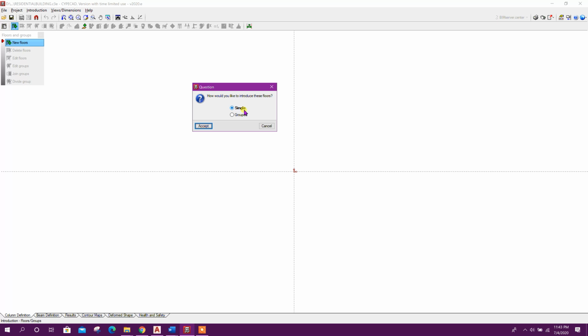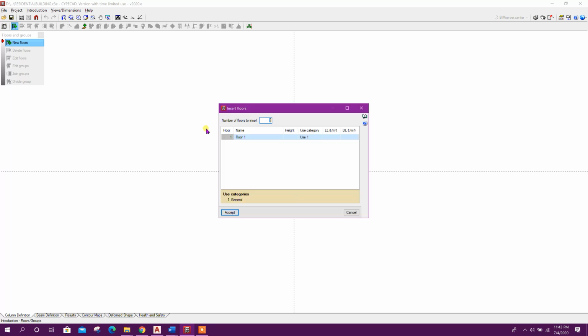First we will go with single floor, except here we will write PB plinth beam, this one height from foundation 2.2 meter, live load here 0, because in plinth beam level there will be no slab.